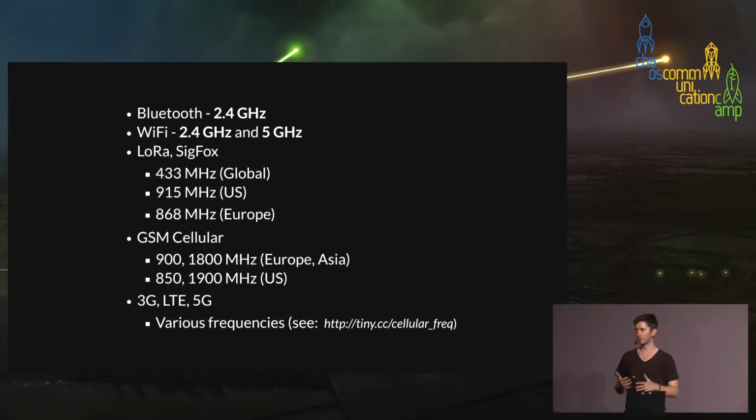A lot of them, as far as GSM and cellular go, are spectrum that's been allocated by your local governing body, the FCC in the US, and sorry, I don't know the European name here. But the idea is that those are pre-allotted to these different technologies. Then there are the more open ones like 2.4 gigahertz and 915 in the States, the ISM bands and things like that. You're going to be operating with all of these different frequencies, but the underlying things are the same.